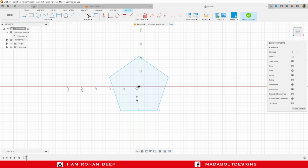Press enter. Here you can see the polygon is not fully constrained because all the sides are blue. In order to make it constrained, select this edge of the polygon and make it horizontal or vertical. Here the icon appears. That means this side is completely horizontal. Now you can't change the length or rotate the polygon. For now, our sketch is completed. So, finish sketch.